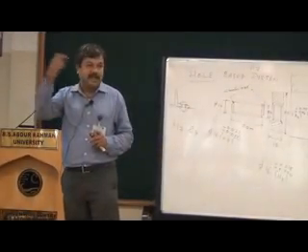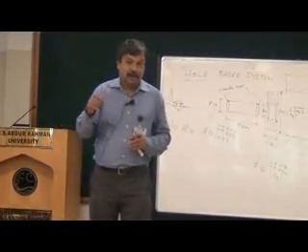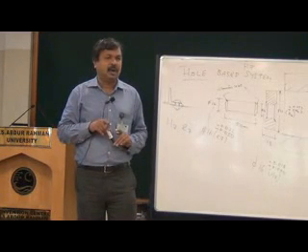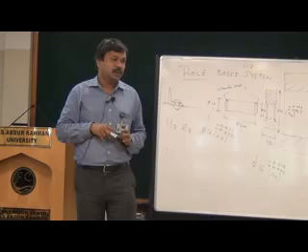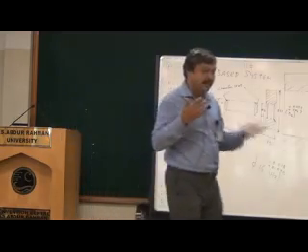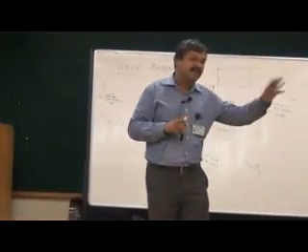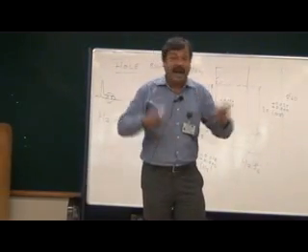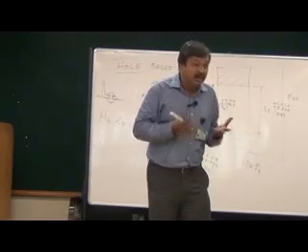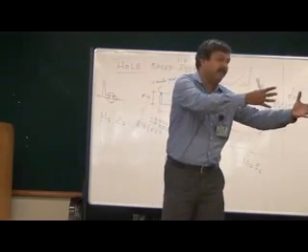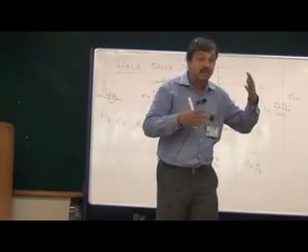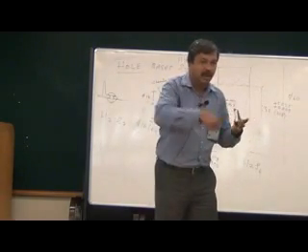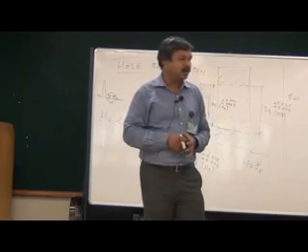Based on the idea of robust design, Taguchi evolved a very, very useful experimental technique called factorial design, which basically helped him to identify the level of influence of each parameter on the performance. You have 10 parameters. How do these 10 parameters influence the performance? You need to study that if you want to make your system more robust.